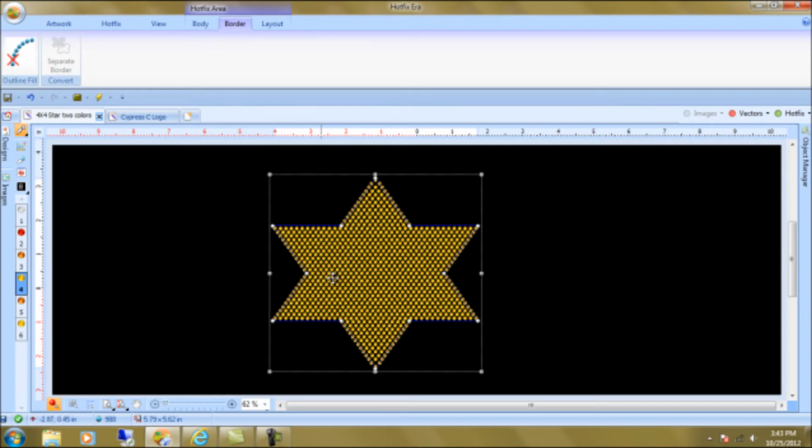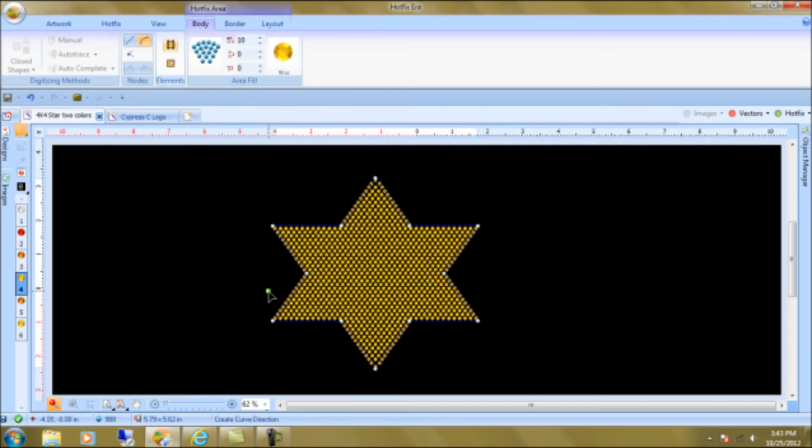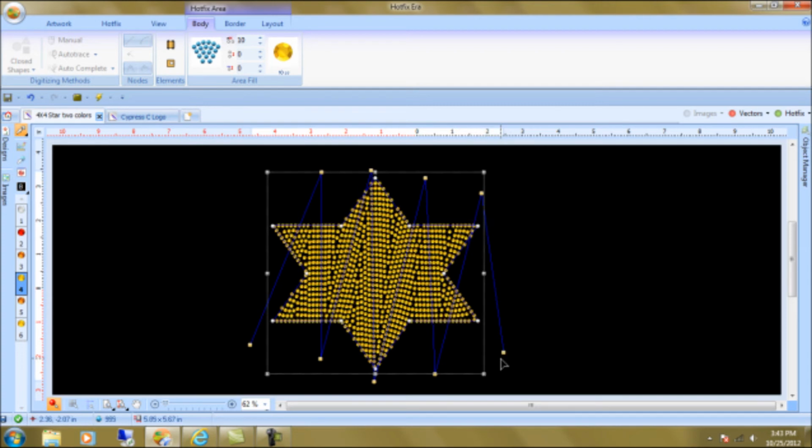Okay, so what I'll do is I'll choose the flexible hotfix fill, and I will use my stitch direction here. If I click on that, if I start from one end, I'm going to hold my shift key because it's going to be straight nodes, and I'll start from one end and I'll just work like a zigzag pattern. What I'm doing is defining how these stones should fill that shape. From one end to the other, going from top to bottom, hit enter, and that's what it does.